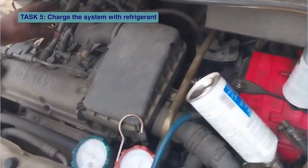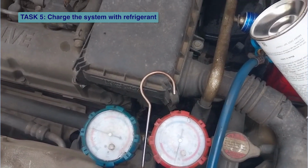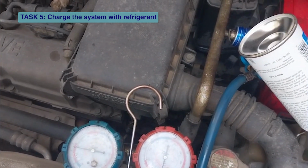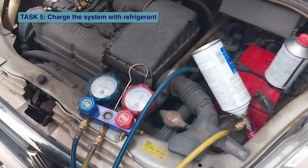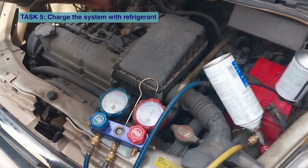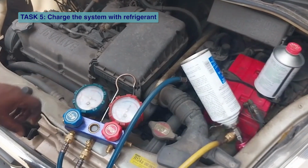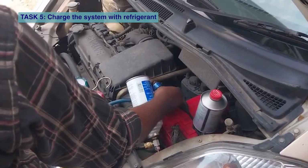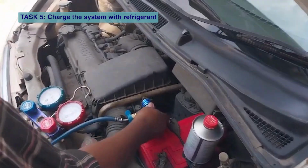Check the pressure gauges regularly during the charging process to verify that the system is receiving the appropriate amount of refrigerant. If the system is equipped with a sight glass, check it to confirm that the refrigerant level is correct. Open the suction port valve knob and let the remaining refrigerant flow into the system.